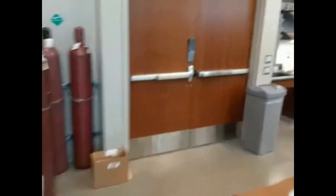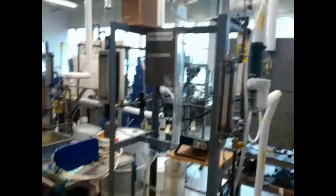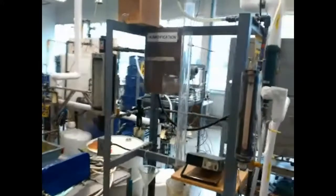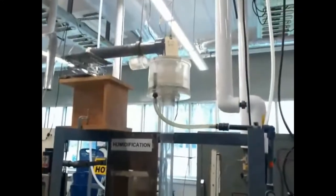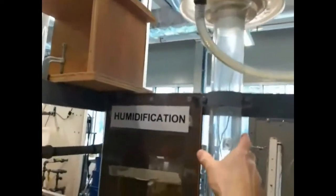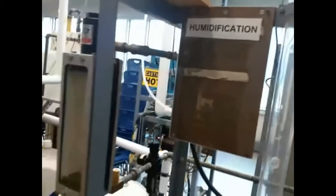So let me move on to here. For the lab, we actually had the lab in November, so we gave safety glasses to all our students so that everybody was safe. This is another unit, a humidification column. Think of a humidifier. What we do is take air and humidify it by pouring water through this column. The water is on the top, and it comes down the outside of the column. The air comes up through the middle and picks up the moisture from the water, and then we can humidify our air.